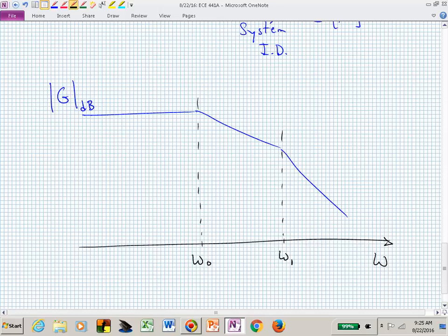And then we had thumbtacks, which were the zeros. That's where we stuck the rubber sheet down, and those are the values of S, the frequency values that cause the numerator factors to vanish. Those are zeros. And we have some overall gain. This is now telling us how the gain of that system moves or changes with frequency of excitation.